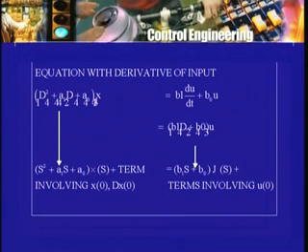What about the Laplace transform of the right hand side? The right hand side is (b1 D plus b0) operating on u, and using the derivative formula it will turn out to be (b1 s plus b0) into U(s). But just as there are the initial values of x on the left hand side, because there is a derivative of u on the right hand side, there will be an initial value of u on the right hand side. So plus a term involving u0 in this case.